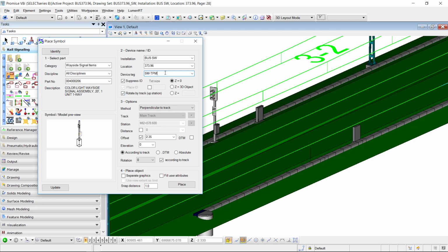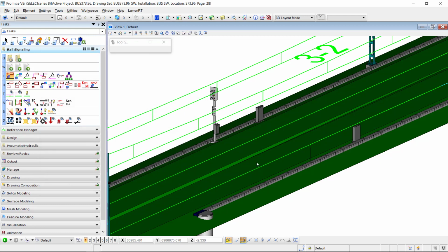And here we can change the name of that, and then we get an option to place a new instance of that particular component. So we call it B, and we will place it down using track and station values, but it will associate this with the side track. And if we place it down, I can then choose if we want to place it on the right or on the left hand side of the track.